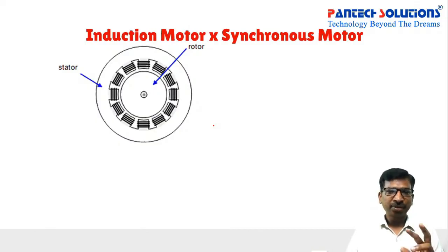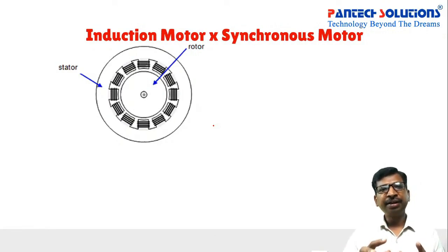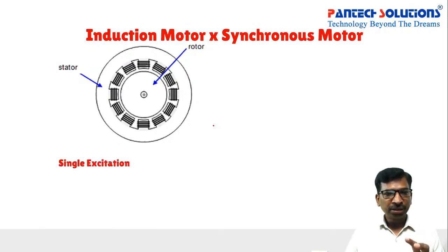In the stator it has a coil. Similarly, the rotor also has a coil. Sometimes it will be terminated with an end ring, otherwise it will be terminated with an external rheostat. So based on your application, you can choose the type.